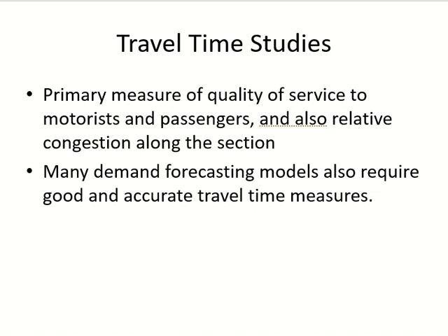That's how travel time studies are separate from speed studies. Speed studies can be done for a short distance, even for a point. But if you have taken travel time for a very small distance, it will not be considered valid. Speed is still considered valid, but the travel time of a smaller distance is not considered valid for traffic engineering purposes.